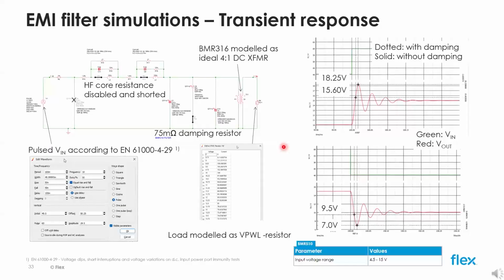As a side note, the ideal DC transformer model is also pushing the limit. I should have included a parasitic output resistance and maybe inductance, etc. In conclusion, even if the problem might be less severe than it appears, a well-damped filter remains preferable.